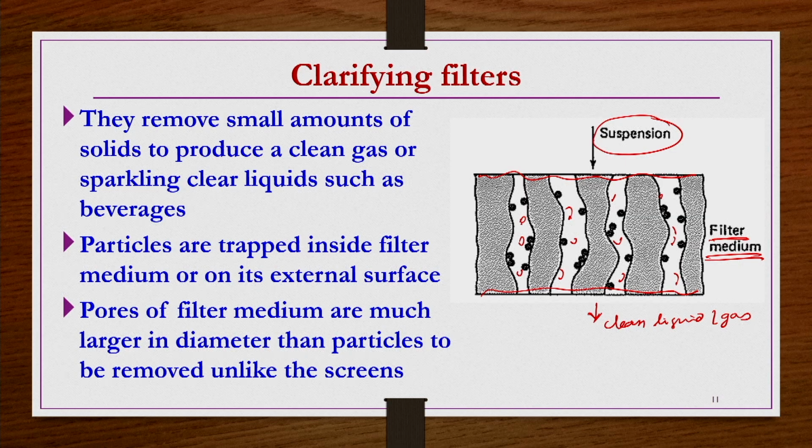Right. So, what is the difference between the cake filter and clarifying filter? Cake filters are in general used to separate a large amount of coarse particles, whereas clarifying filters are in general used to separate a small amount of fine, smaller particles.